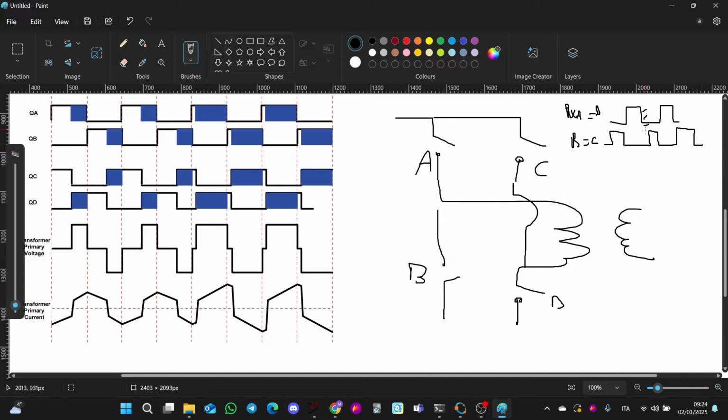Of course, there is the dead time, and the primary voltage of the transformer becomes like this. When the PWM A is on, it means that you have Vin here. And then in the full bridge, it goes to minus Vin, but there is, of course, the dead time, and so it goes like this. Yes, my drawing is so horrible, but it is like this, okay? So let's see what happens now in the phase shift full bridge.